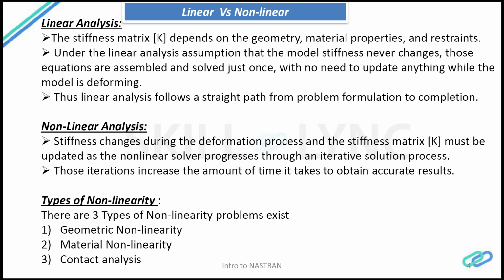Since the stiffness and the behavior of the structure doesn't change, whatever the loads, the internal loads of the structure, that is the stresses, stay within the linear elastic region and behave according to Hooke's law. Thus the linear analysis follows a straight path from the problem formulation to the computation. It is a very straightforward method.